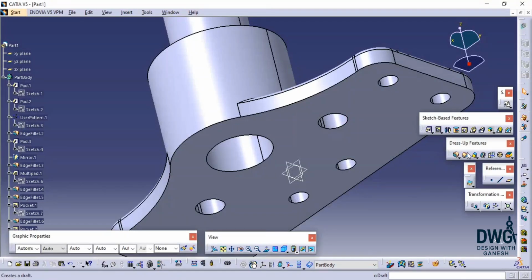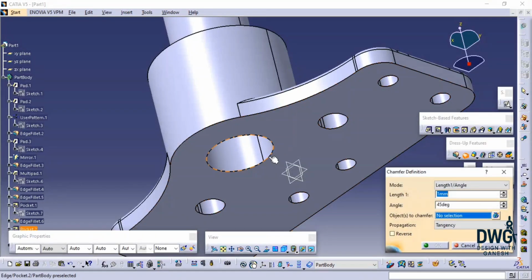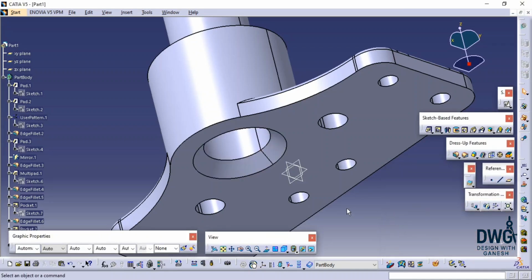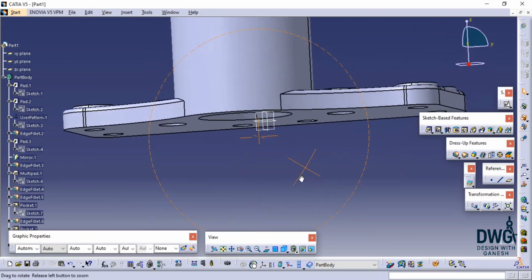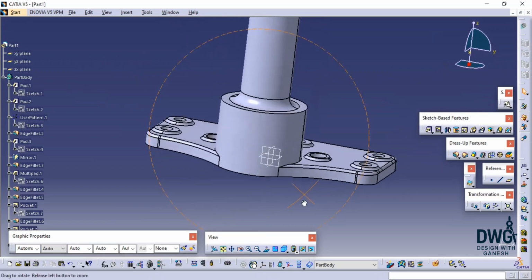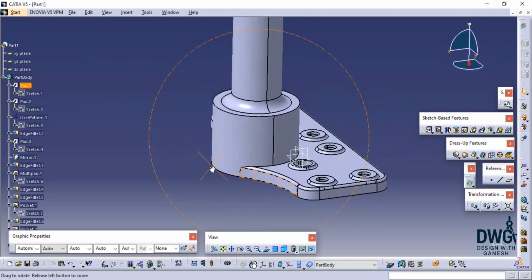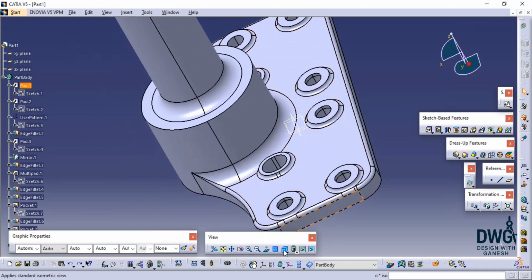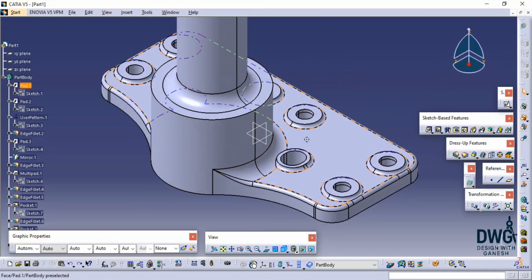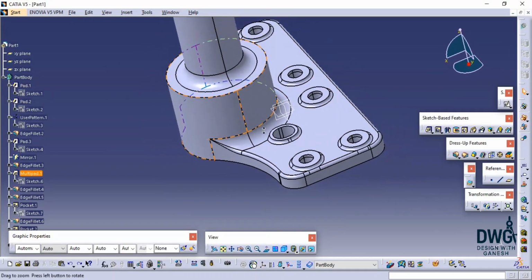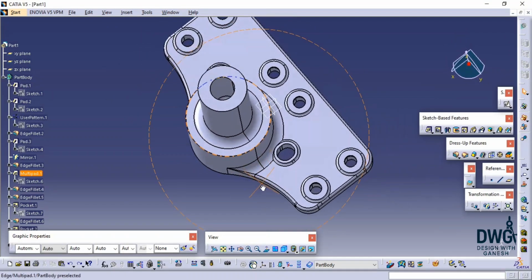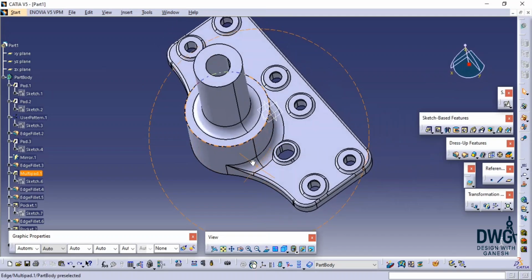That's it. And one more thing that we need to do is use a chamfer, click on this chamfer and select this edge, and you keep it as a 10 mm. So it is 1, so update it to 10, enter. Okay, so now the base is also completed. And the next thing is, we need to create a plane for making this stiffener. So how can you do that?